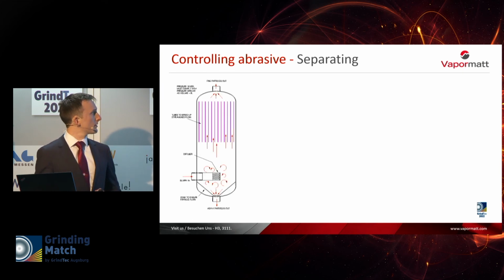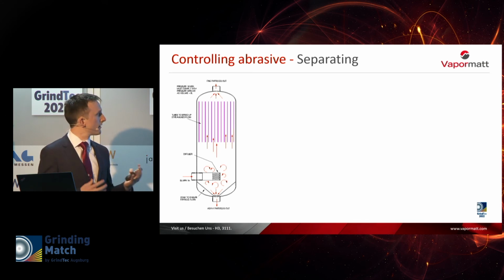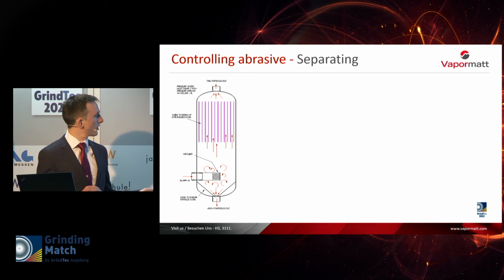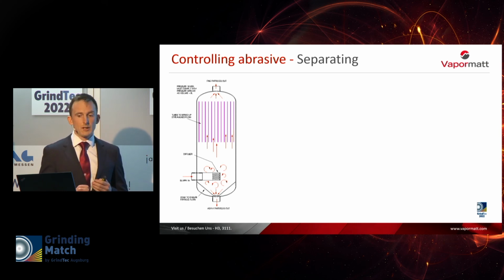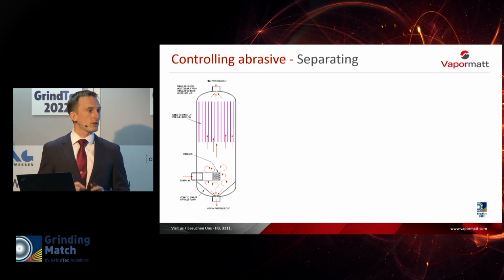The first is through a patented technology called elutriation, and you see here an elutriation tower which is used to help with this. This is the most controlled and configured way to remove broken particles, and the flow rates of the slurry are slowed down through different orifice plates at the top and the bottom of the tower. This gives very, very tight tolerance on the abrasive, which results in much tighter tolerances on the blasting.